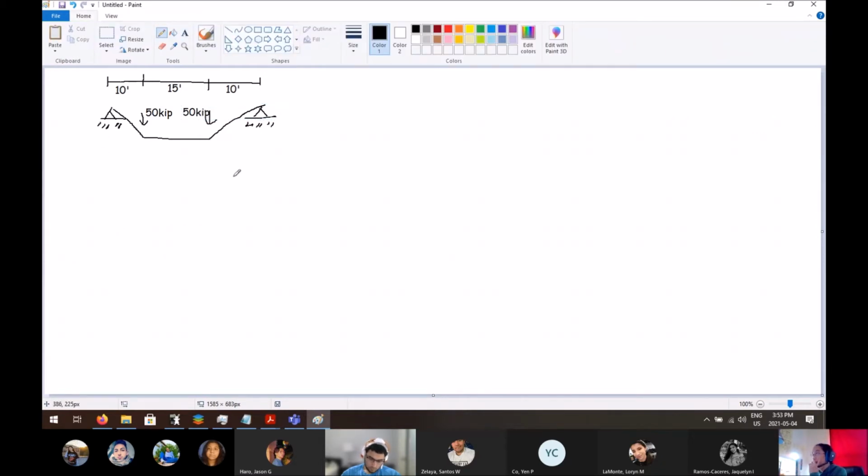Fun stuff. Right, so remember pins, there are two reactions. There's an X direction and a Y direction. Reaction in the X for A, we're gonna call this A, B, C, D. We have RYA, RYB, RXB, right?